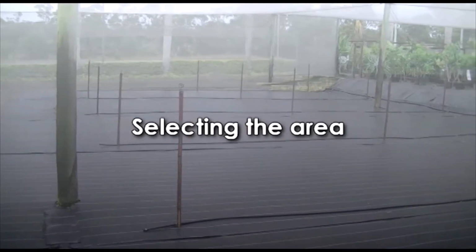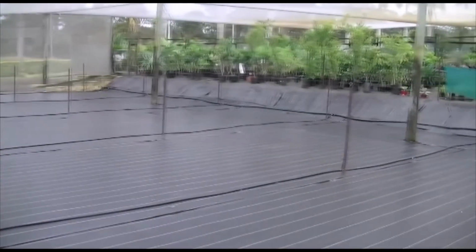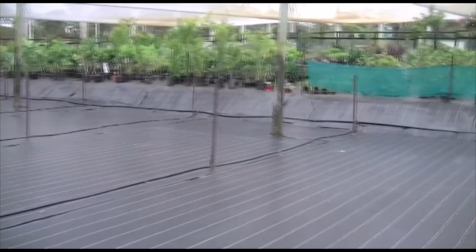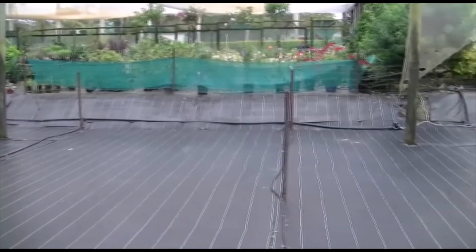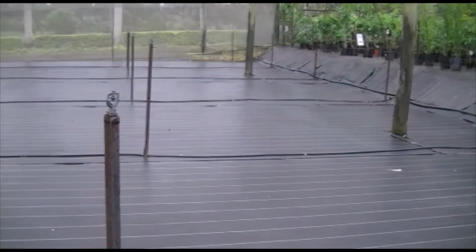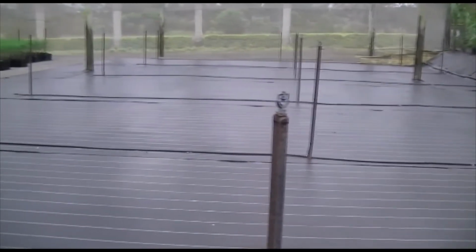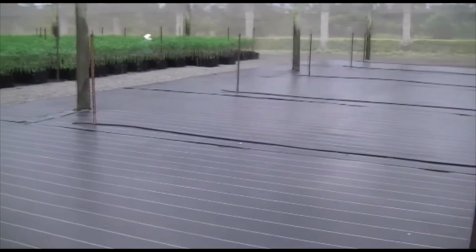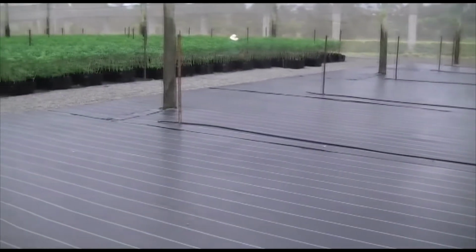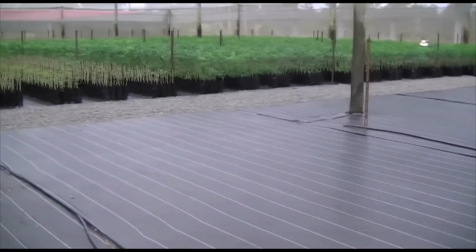Next, it is necessary to select the area to be tested. An area with no plants in place, where the catch cans can be located, but representative of the irrigation zone, should be chosen. It is best to test an area as large as possible within the irrigation zone, and wherever feasible, include at least one outside edge of the zone to be tested. Growers sometimes are aware of underperforming areas within an irrigation zone and may wish to include those in the test.